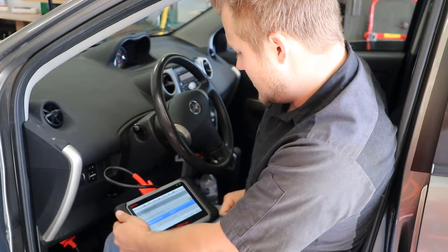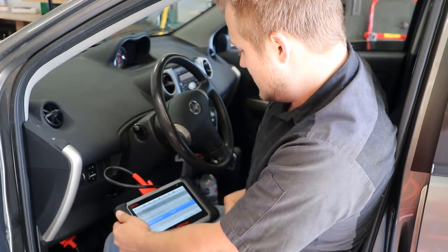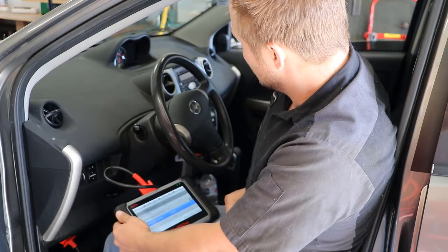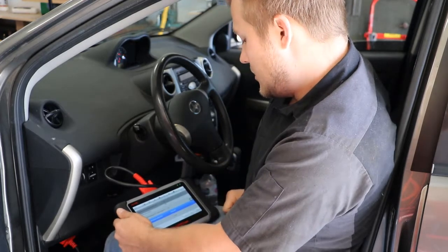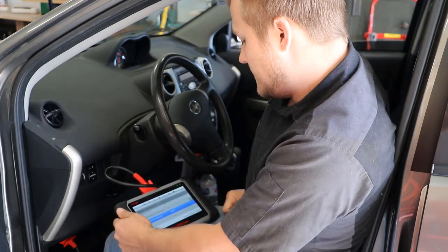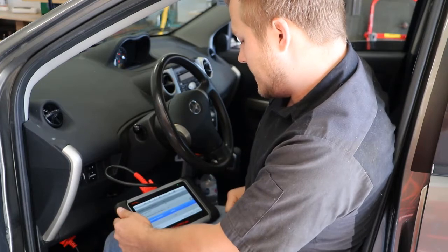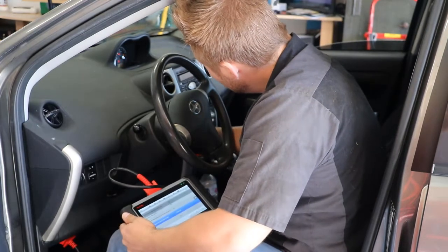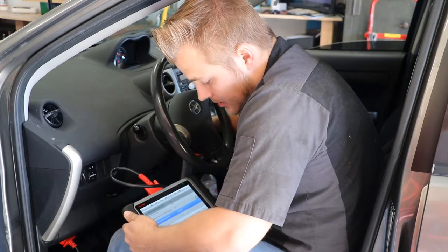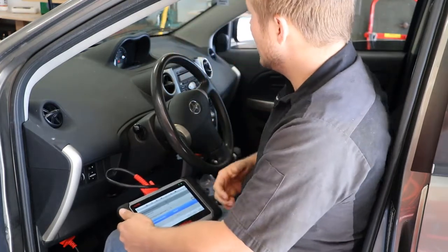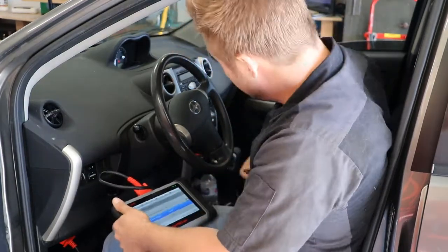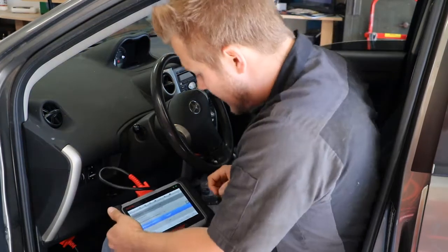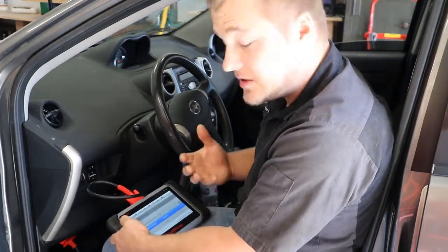Yeah, it's definitely not too much change here, so we might have an issue with the purge valve. Yeah. So already it's giving me a sign that the car's been warmed up, it has been running, so obviously it's past that phase. But still, there was a change in the initial beginning, but I think the valve itself is getting stuck, or unfortunately isn't quite getting what it, you know, maybe it's sticking, maybe the solenoid. So we're actually going to go take a look at it and do a manual test on that valve.